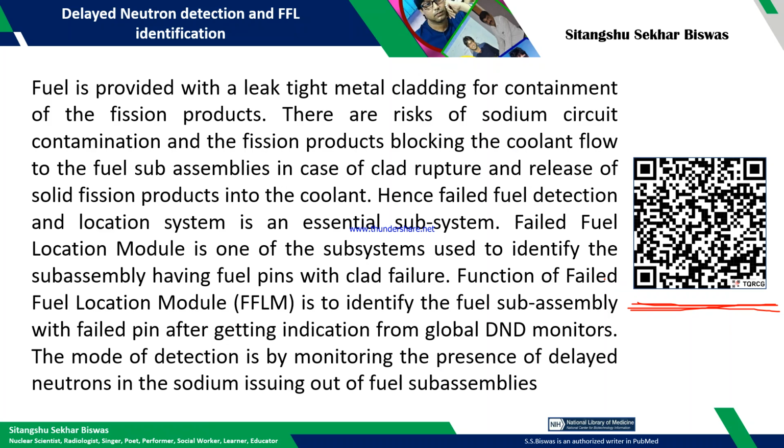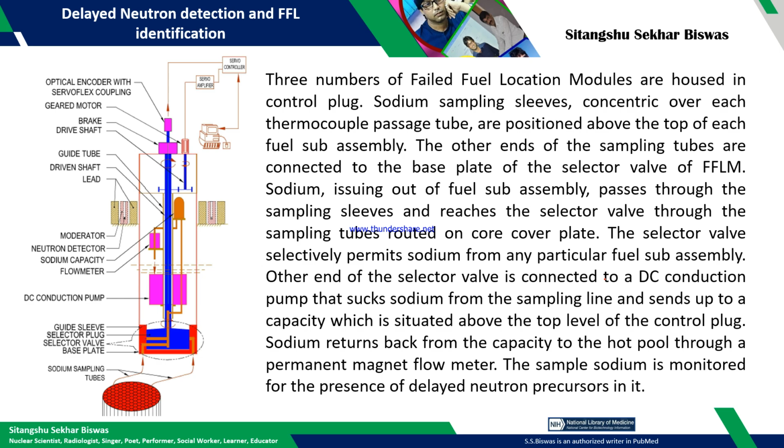If, due to clad failure, they mix with the coolant, and you take it and check whether delayed neutron is present or not, from that you can easily understand that the clad has been ruptured. So this is the basic technique.